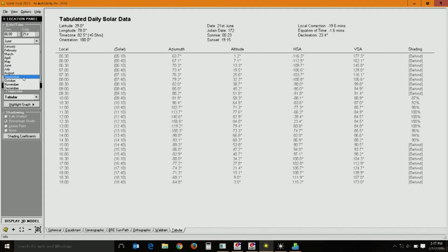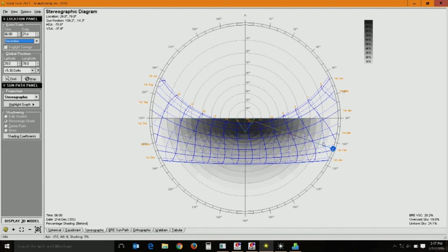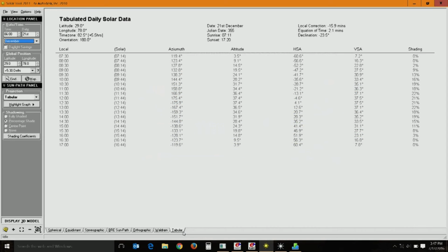On the other side, if you look at December, this shading device may not be effective because you have direct solar incidence most part of the day. This is December. In the table, the maximum efficiency you are getting with this shading device is 22%, and some part of the day it is 0, that is there is no use of this particular shading device or it is not offering any effective shading. So, it slightly increases during noon, it is close to 22 percentage, then eventually it drops down.